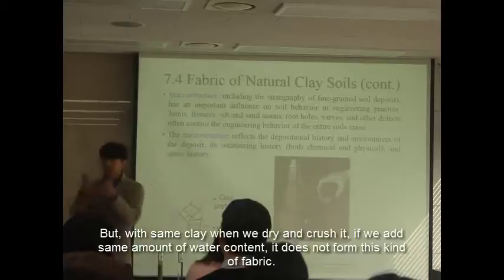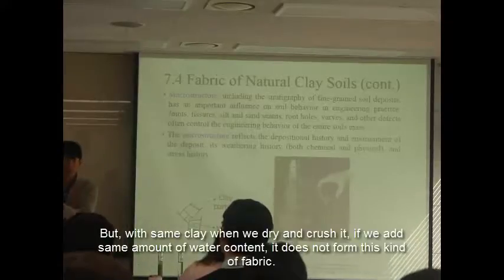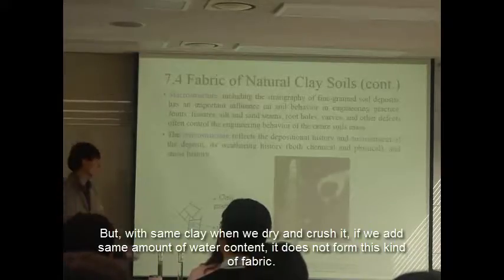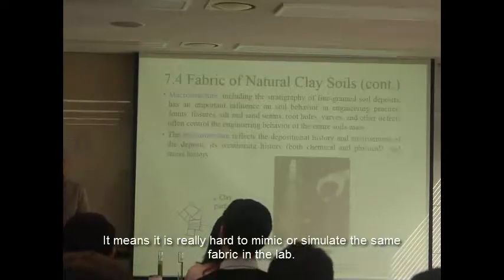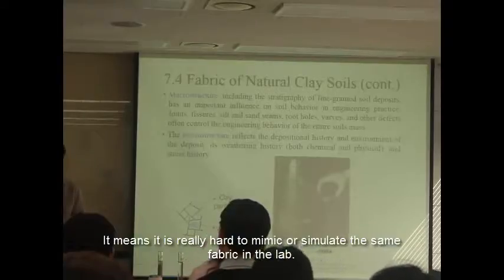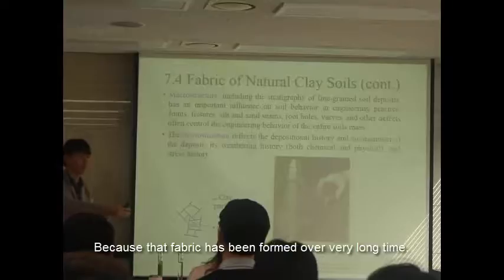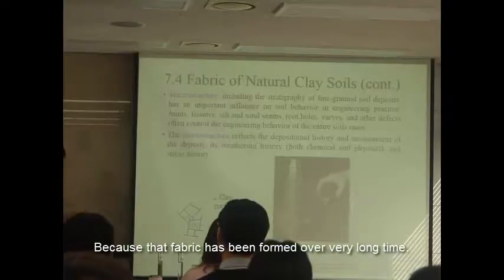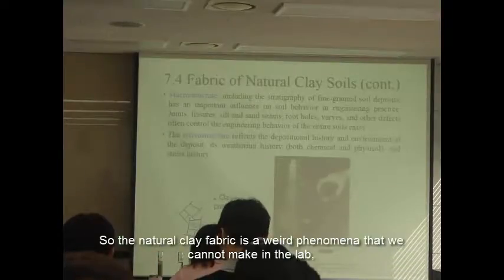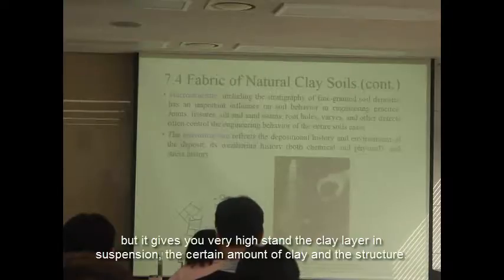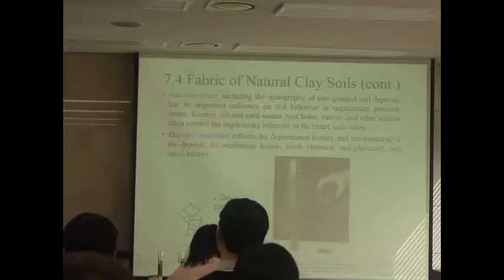But with the same clay, if you dry it, crush it, and add the same amount of water content, it doesn't form this kind of fabric. So it's really hard to mimic or simulate the same fabric in the lab, because that fabric has been formed over a very long time. Natural clay fabric is a very unique phenomenon. We cannot make it in the lab, but it gives very high strength. That's why a clay layer can sustain a certain amount of weight and structures.